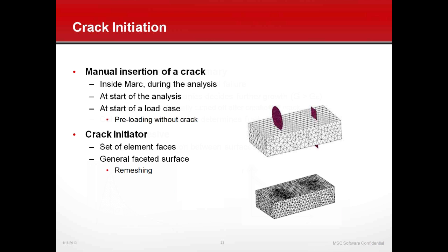Okay, moving on to the next part of the presentation, the initiation of cracks. We introduced the option now to insert a crack inside Marc in the analysis. Previously, normally you just create your crack in the preprocessor and run the job with that crack. Now you also have the option to do that inside Marc, and you can add the crack at the start of the analysis. You can do it to start at the load case. You can preload without a crack and then add it. But you, as a user, decide where the crack should be.